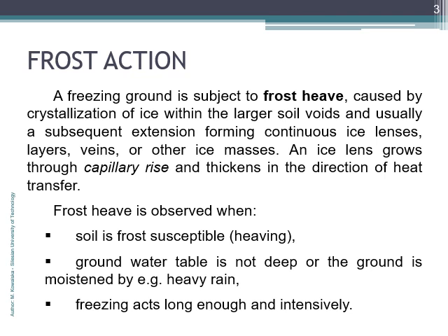Because when the temperature drops fast, so for instance quickly it becomes lower than -10 Celsius degrees, then the water has no time to flow to the freezing front before the material totally freezes. And as a result, no more water can move to the freezing front. In this case, the frost heave or the frost expansion will be quite low.